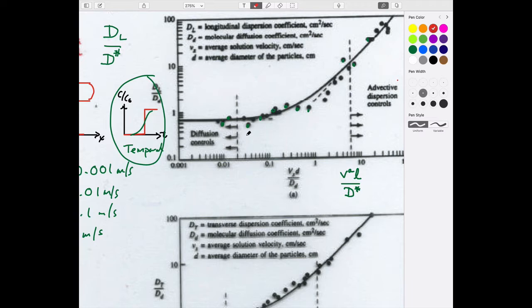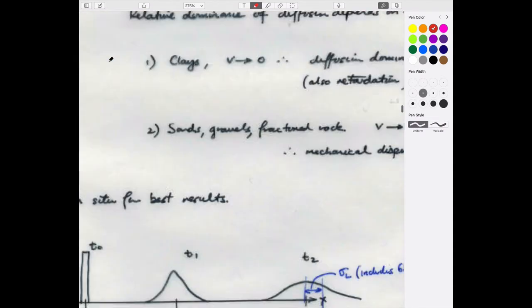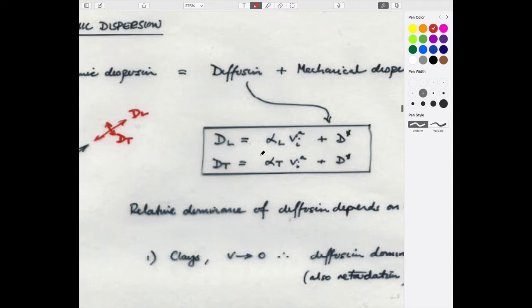The first feature is that, as you'd expect, at very low flow velocities, which are what these are, you'd expect that the diffusion coefficient you get would only be the diffusive diffusion, no advection terms. So the value of this coefficient you expect would be 1. And so you kind of get that. It's a little less than 1, but not more. As you get progressively higher and higher velocities, then the magnitude of this advection affected one is probably going to be larger than that because we expect it to conform to this expression here.